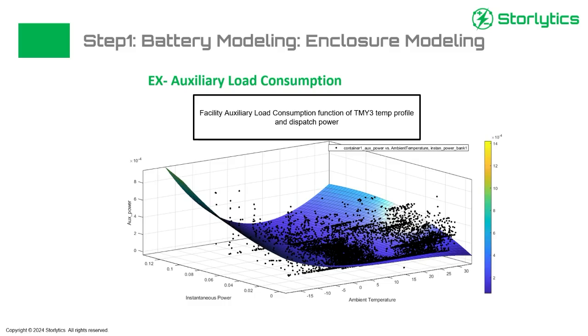So next here, this one's also particularly important for lithium systems because they're temperature regulated, which means they're going to have an HVAC system attached to them performing for the entirety of the life of the project. So it becomes important to model how much load that's going to end up consuming if you want to account for the running cost of the project.